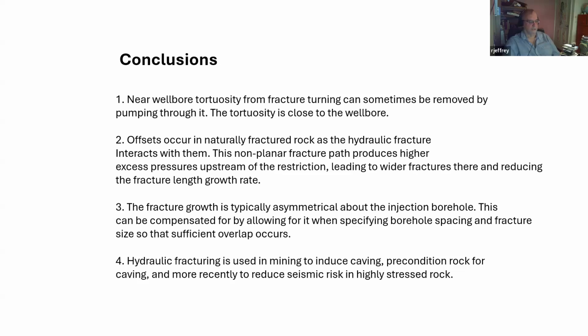Well, a large part is practicality. We have experience now preconditioning in sandstone, conglomerate, and hard naturally fractured rock for metal mining, and have found that 2.5 meters is adequate to precondition the rock.